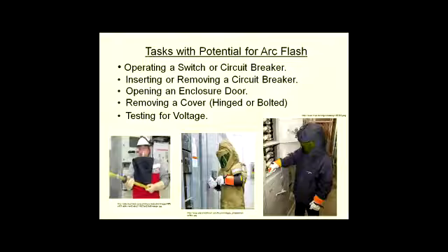Operating an enclosure door. We'll look at some of that. Well, over here there's a dude opening an enclosure door, right here. Okay, that can cause an arc flash. Removing a cover, hinged or bolted, or testing for voltage.